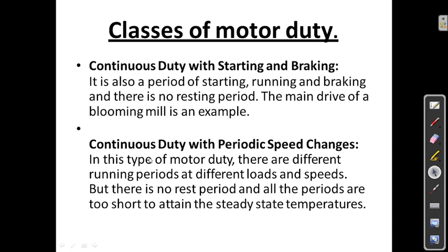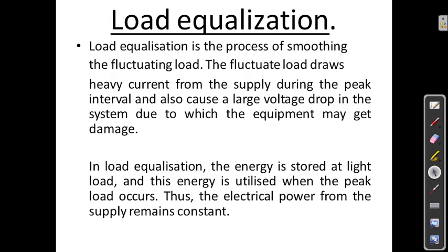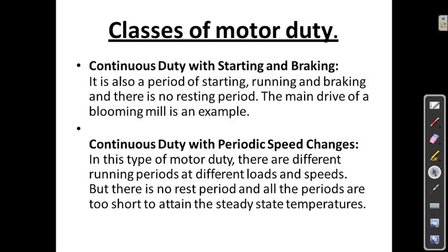Then the continuous duty with the starting and braking. It also has periods of starting, running and braking, and there is no resting period. The main drive of a blooming mill is an example of this continuous duty with starting and braking.